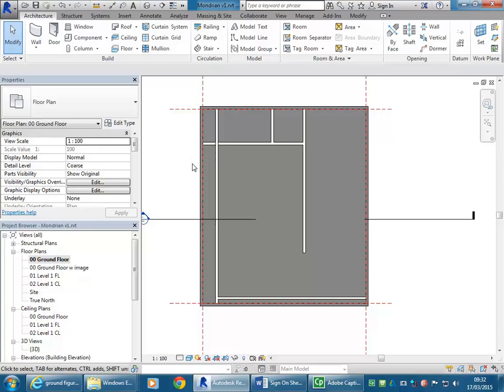And so I'll use tab just by moving my cursor to the edge of the wall where I know the floor is as well underneath. Then I'll press tab. First time it just gives me a chain of those 4 walls. I don't want that. So tab again.